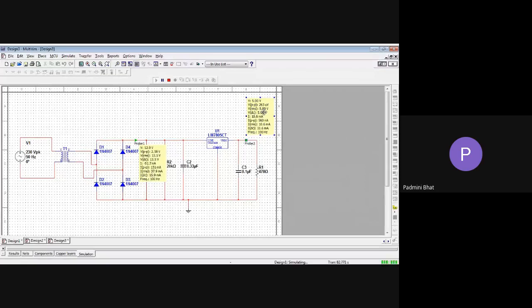If you use 79 instead of 78, the configuration itself is different, so it is not working like a regulator. It is not pulling down, it is not comparing, nor is it like any ordinary amplifier. So it gives you random answers. LM79 with proper C and R values gives you minus 5 volt. If you don't do all those, it gives you a random value. That was one doubt.